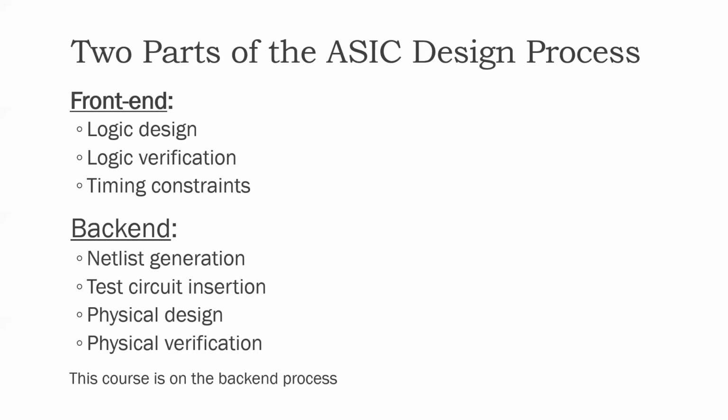Once the logic is designed and verified and the timing constraints are defined, then the back-end of the ASIC design process commences. And this class is completely focused on the back-end, and the back-end largely comprises physical design. But there is also another aspect to chip design that we consider as part of the backend, which is test circuit insertion.